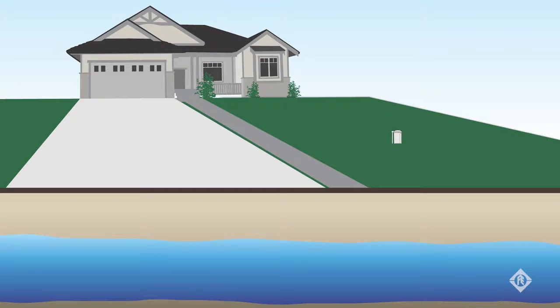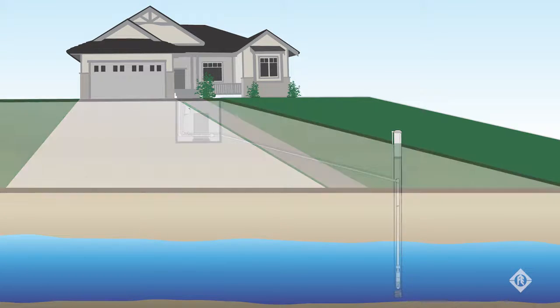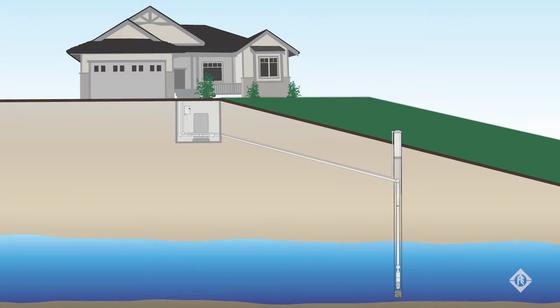Let's discuss how to choose a pump and how they're labeled to help with this chore. The data we need to have is the following. 1. Static level and pumping level of the well at the required flow rate. You need to know how far you'll be lifting water out of the well, tank, or open body of water. This height is based on the distance from the surface of the water to the point of use. In a well, the water level will change as we draw water from the well, so depending on the well's capability to supply water, that change in level can be dramatic.